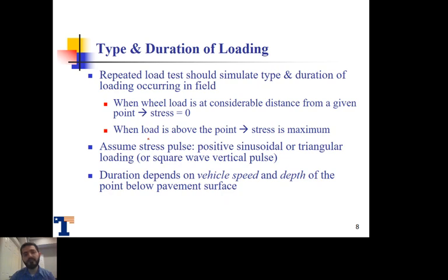So how about the type of the test and the duration of the loading? The type of the test, as I mentioned before, is a repeated load test that should try as much as we can to simulate the type and duration of the traffic loading occurring in the field. So when a wheel load is at a considerable distance from a given point, that means the stress is equal to zero. The wheel is far away from the point of interest, so the stress has to be zero. And then when the load is above the point, this is where the stress is maximum at that point of interest.